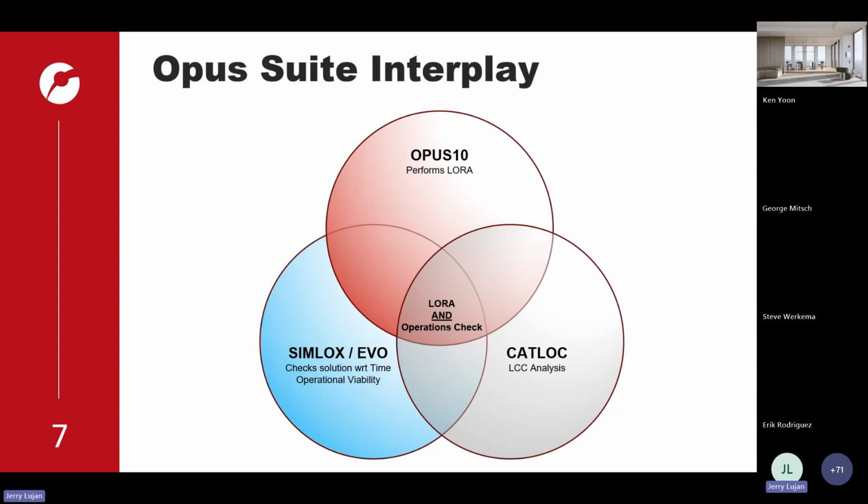Availability is meant to be an insight into how many missions that system can perform, right? The A sub O. And that is more resident on the missions themselves. So having a high availability is good, but let's say we have an unreliable system, it doesn't have a very large MTBF as a system, let's say 12 hours or something like that. Well, if your mission lasts more than 12 hours, the average system will not be able to complete that mission.